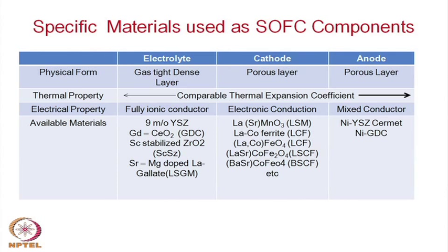Now, one thing also is important here: what will be the thickness of the layer? Thickness has a very important bearing on the overall performance of the cell, because the higher the thickness, the higher the resistance, which gives rise to higher internal impedance of the cell. So, one cannot draw a large current if one wants to. If the thickness is large, then the resistance is high and the current density of the system as a whole reduces. So, you cannot draw large currents.